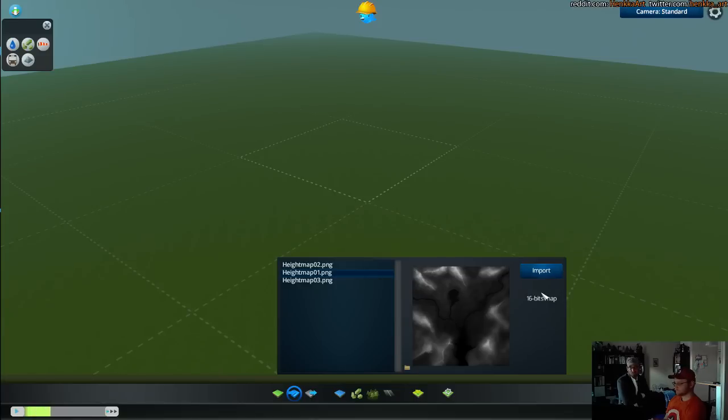You could use software such as World Machine to generate the topology in the first place and export a height map from it that you can directly import here. You should set the resolution to be 1081 by 1081. If you don't respect this, the game will upscale or downscale your map, which will result in funny smoothing as well, which you may not want. So respecting the resolution is quite important.